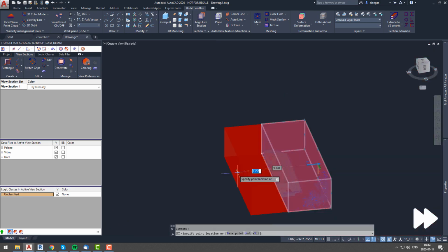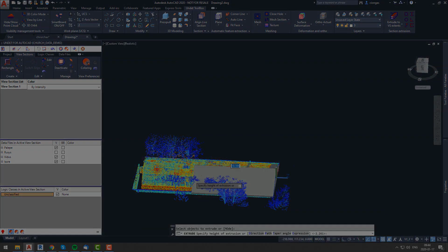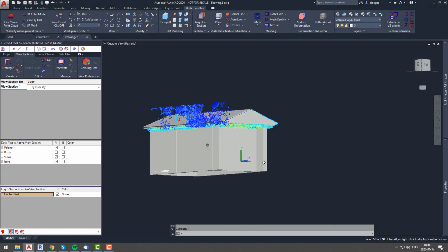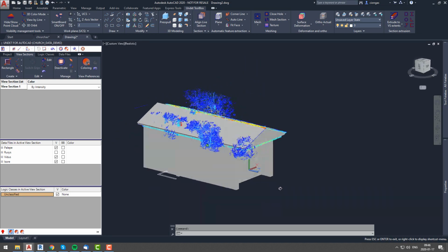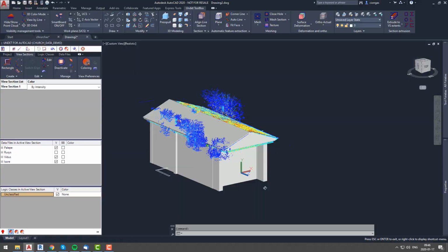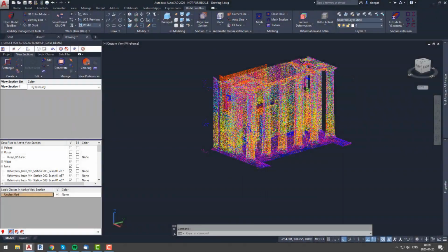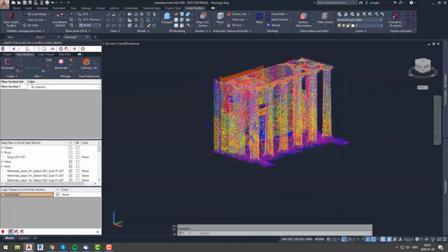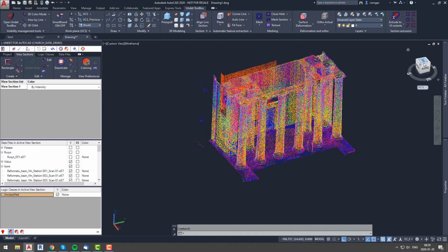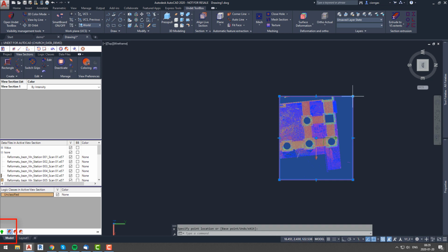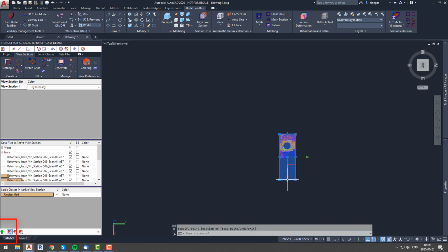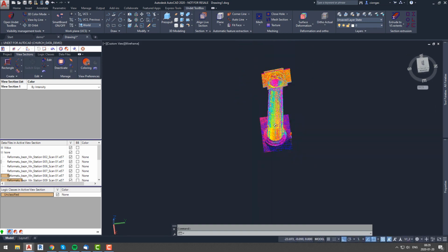At this point we can say that the majority of our 3D modeling workflow is specifying the correct UCS, drawing the element that we need, and then using 3D modeling options to shape that element. So now we will go ahead and model some elements in a higher detail level. We will start with this column. To be able to make the most accurate model, try to work with view sections that have a green indicator as much as possible, since it means that you are seeing all points.